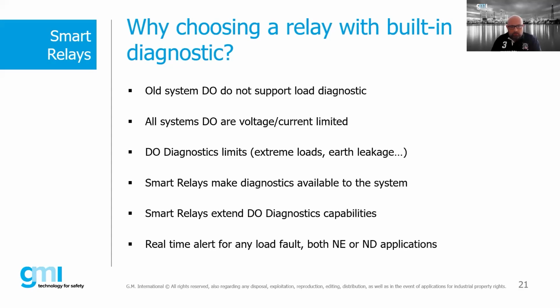Why we should use a smart relay? Nowadays, a full diagnostic of the loop is typically required, but many systems do not have this feature within their digital output card. So in this case, the smart relay is what introduces the diagnostic. In some other cases, the systems have their own diagnostic, but in many applications, they cannot drive the load directly because of their current and voltage limitation.